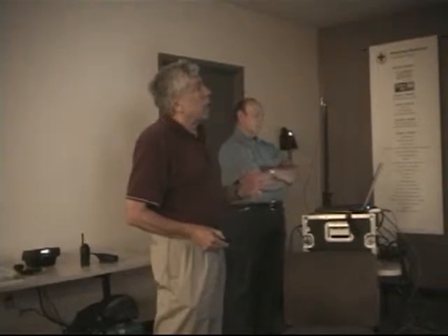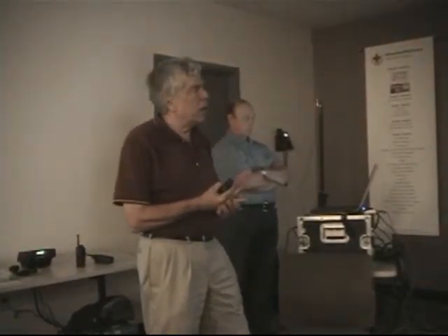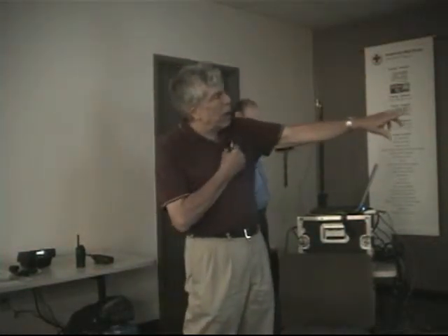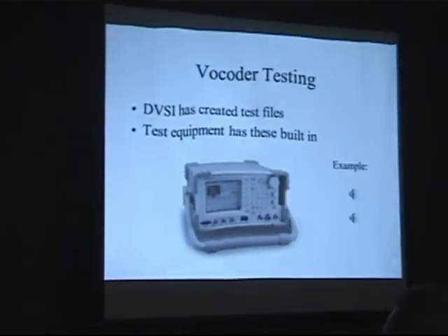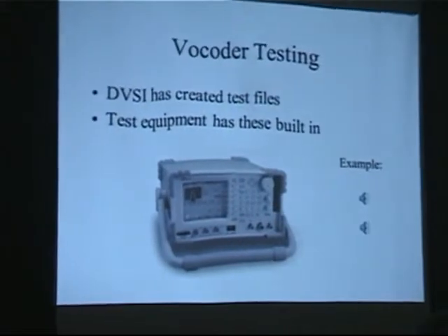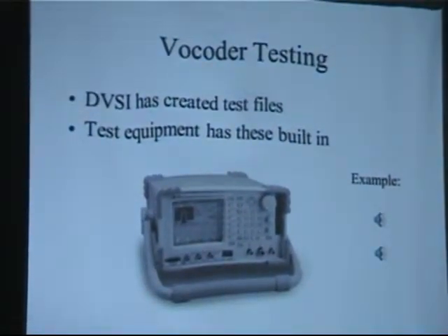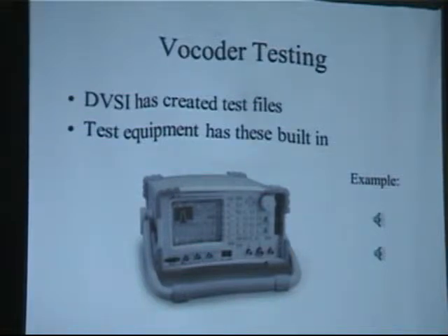So now how do we actually test that vocoder to make sure it's doing the right thing? The company, DVSI, has created test files specifically for that, and it's built right into test equipment like that Aeroflex analyzer that's pictured there. And it simply transmits the same set of phrases repetitively.